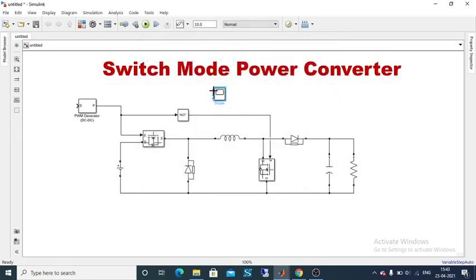In the first port we can connect the PWM generated output. This is the gate pulse to the first switch, which is going to be seen in your first port, and the gate pulse to the second switch is going to be seen in your second port. Fine, very good. And the output voltage across your load also we can measure.